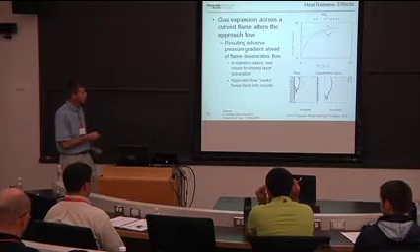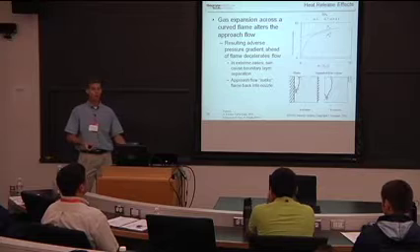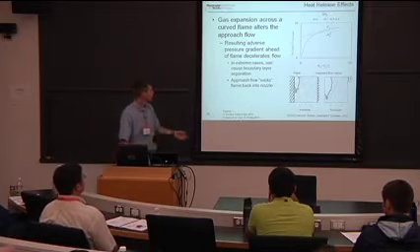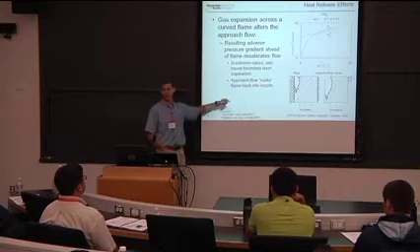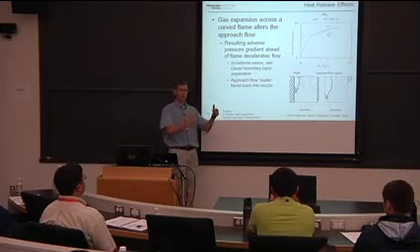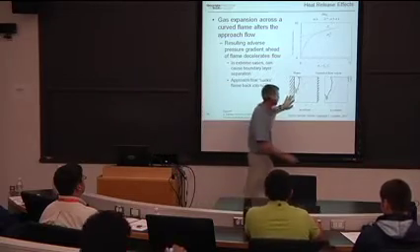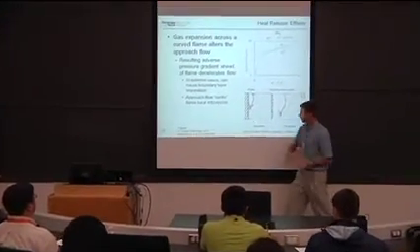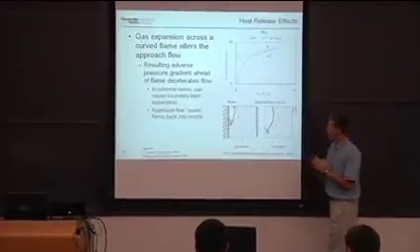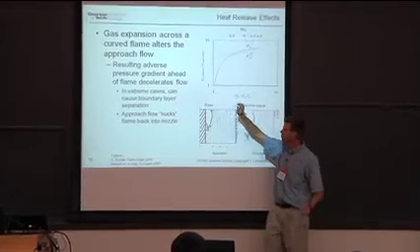And in extreme cases, what can happen is you can actually cause the boundary layer to separate. And what happens if the boundary layer separates? The approach flow is sucking the flame back into the nozzle. Your flow, which is nominally in this direction without a flame, as soon as you introduce heat release near the walls, is going backwards. And actually, these are some really nice images taken by the group at Lund in an Experiments in Fluids paper from 2010, showing this exact phenomenon where a flame causes boundary layer separation.